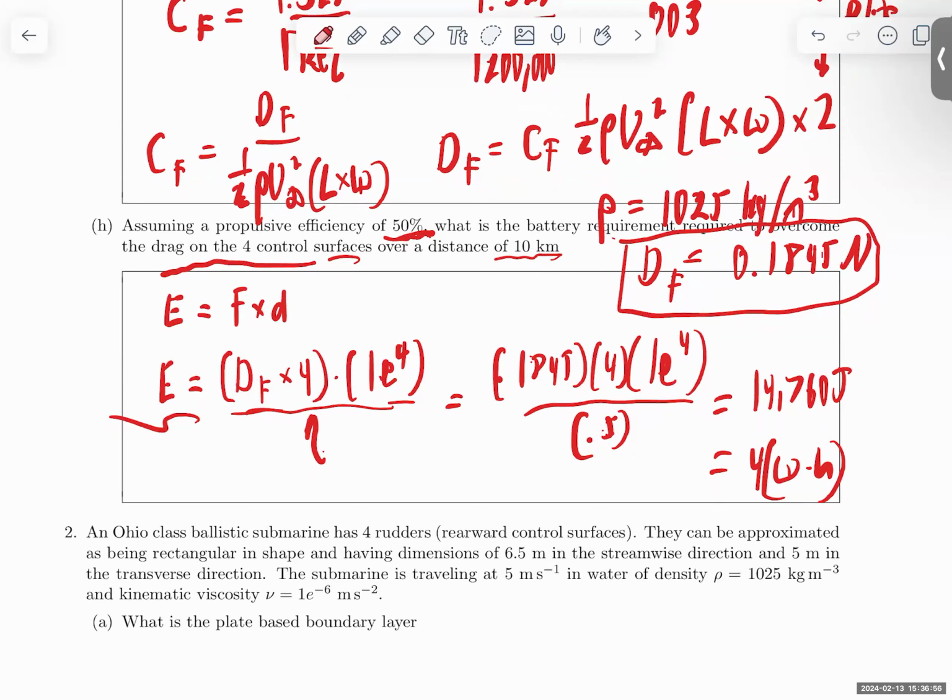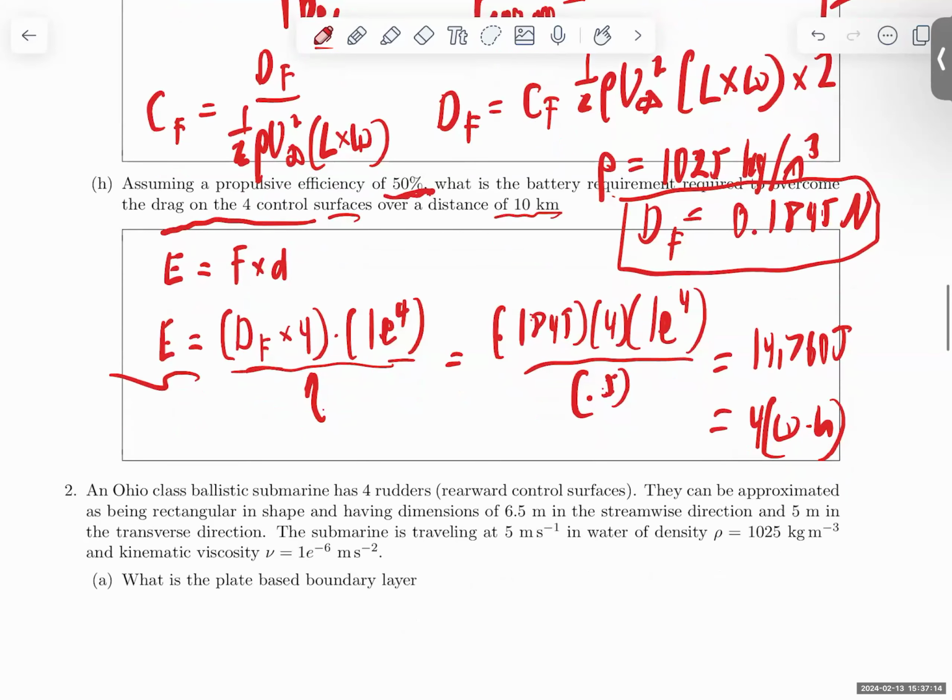Then you have what are called the hotel losses, dealing with whatever systems are running on board. For AUVs with sonar and other very energy-intensive sensors, sometimes that's the dominant form of energy consumption. Depending on other sensor sets, the hydrodynamic resistance may be the dominant form of energy loss. It really depends on what you're doing.